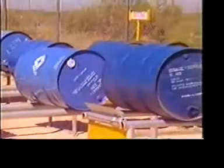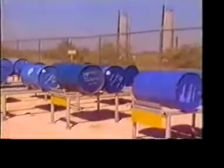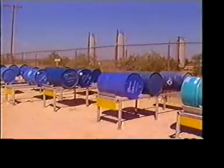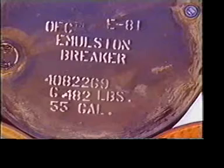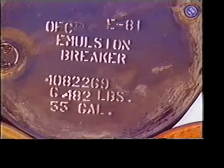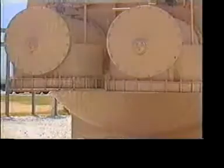The relation of chemicals to temperature is another important factor to consider. Usually, less chemical is required to treat a warm emulsion. However, the savings in chemical costs with higher temperatures may be offset by the loss of revenue caused by gravity and volume losses in the oil and increased fuel costs.